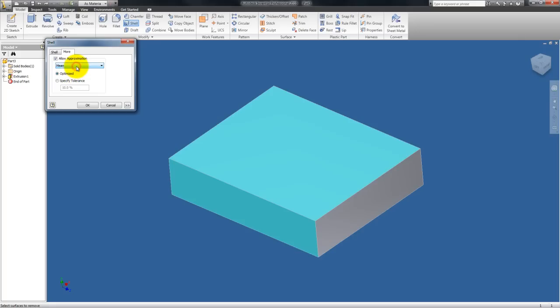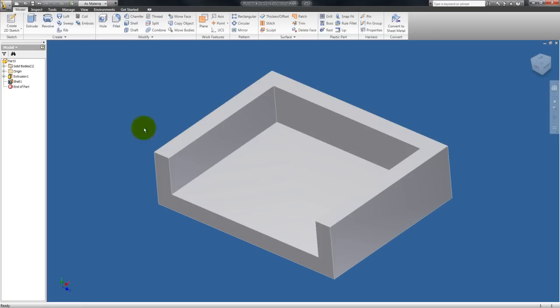This is really for when you're making parts for an assembly and size is critical, but also this shape will end up being exact because it's a simple shape, no curves, it's not a changing profile or anything. So if we go back to shell and we go outside this time, 0.1 inch, you'll see that now the surfaces that we had before, those are now the inside, and it is gone, and this will be 0.1 inch, this will be 0.1 inch, and this thickness will be 0.1 inch.